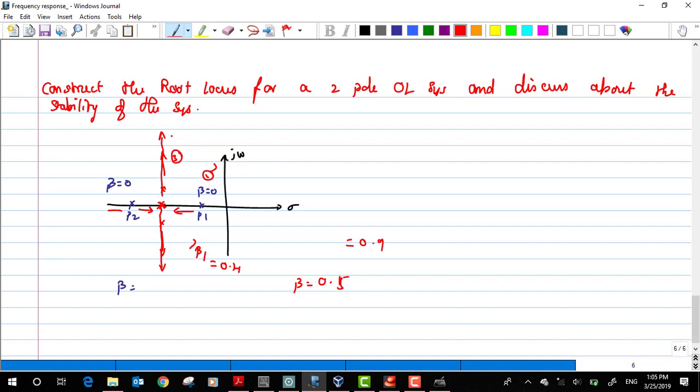All the poles are staying in my left-hand side. I guess you might know that as I keep increasing, these poles will go towards the zeros, which are somewhere at infinity. So that's all fine. For a system that has a single pole or 2 poles, the system will always be stable. That is a conclusion I can derive from both these examples.